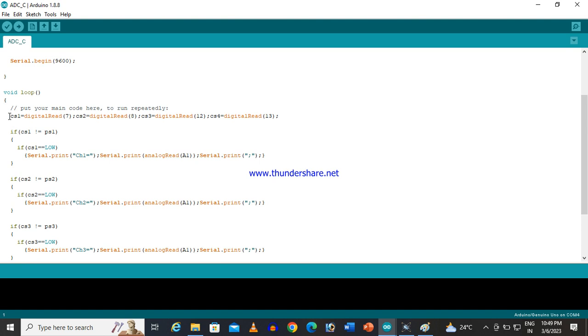First I read all the current states by reading the status of all the selection bits. When the toggling takes place, meaning the falling edge, the current state and the previous state will not be the same, because the transition takes place from high to low, and once the transition is complete, it will be low.